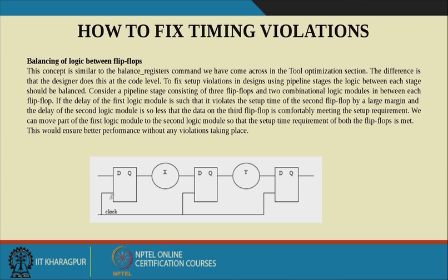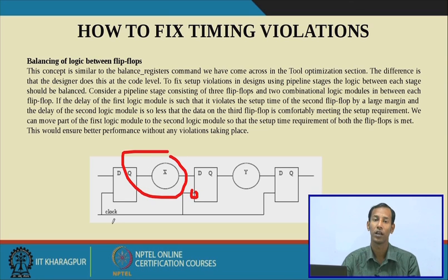There is one term here, that is clock domain crossing. As we are using only a single clock here, it is very much easier. Suppose two registers are there, one driven by a clock 1 source and the other driven by a clock 2 source, and in between them there is a combinatorial circuit.